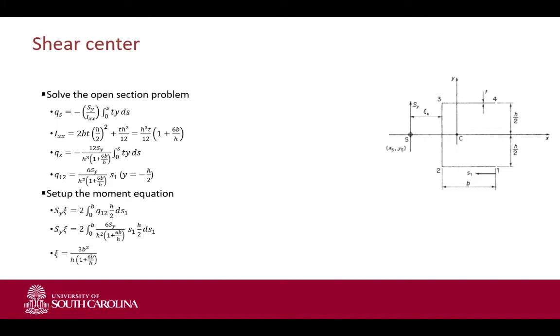And we don't even calculate the shear flow in, say, 2-3, because we take the middle point between points 2 and 3 as our moment location. Because the shear flow, and therefore the shear force, acts through that location, it will have no arm, and therefore creates no moment. So by just looking at the image and the problem, you can reduce the complexity of the problem immediately. If this was an exam question, you don't have to blindly calculate all the shear flows and then determine the shear center. You can choose your location wisely and then calculate the corresponding components to solve the problem.